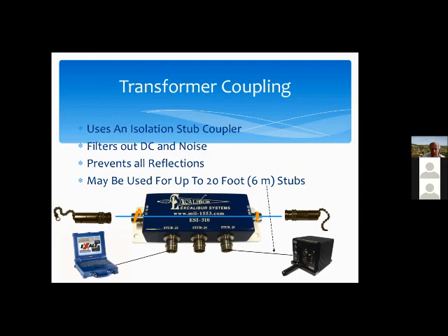Let's say this side has the wire attached to the other, then on this side I want to put the terminator on. Similarly, the other coupler is going to have the bus attached to it on one side, and on the other side, I'm going to put another terminator on, and then I'm going to have a clean signal. If you use a coupler, you're allowed to have 20 feet between your bus controller or RT and the coupler. And it's a very clean signal.